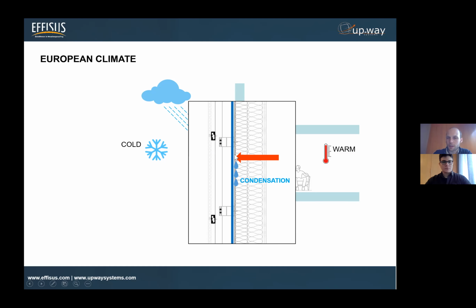And as this vapor would be blocked just in here, just after crossing the thermal insulation layer, this section in here will be much cooler than the one just inside the insulation layer, and so it will turn into liquid water, of course, as it finds the coldest surface. And then one possibility would be to create a breathable membrane just in here.